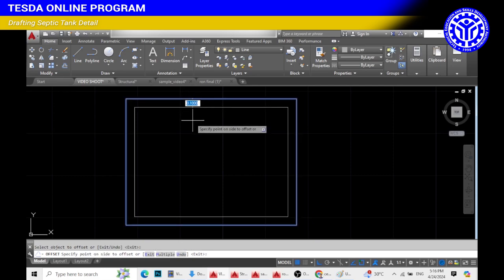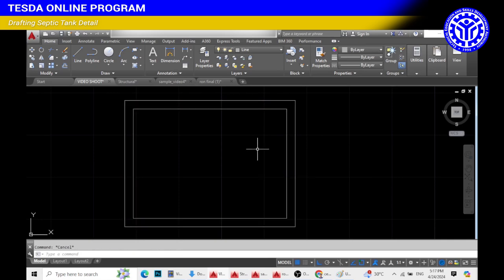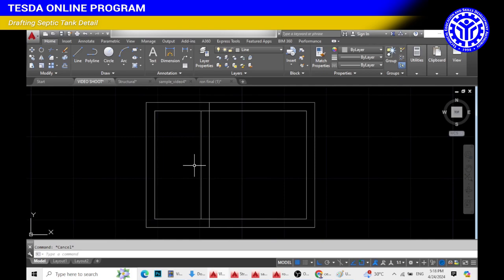The septic tank layout has 3 chambers. Select the septic tank layout and use the Explode command. Indicate 1.25 meters on the measurement. Drag the vertical line inwards to create a division. On the smaller chamber, create a line using the Line command to divide it into 2.